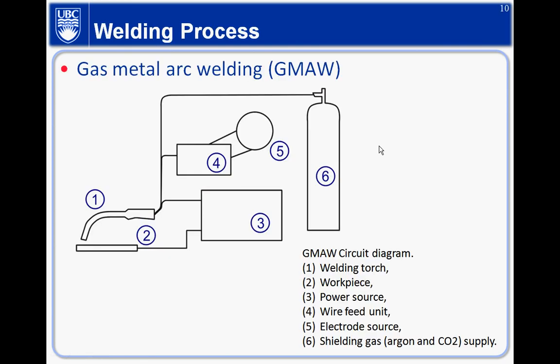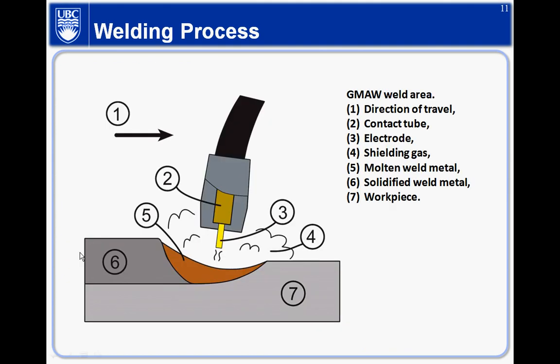Okay. The gas metal arc welding. There's a wire automatically feeding through here. So it's not a stick; basically it's an automatic wire, and the wire is the electrode. And then there's this gas here, basically helium or any other inert gas. The inert gas is applied to the welded joints to propel all the oxygen or nitrogen out of the location here.